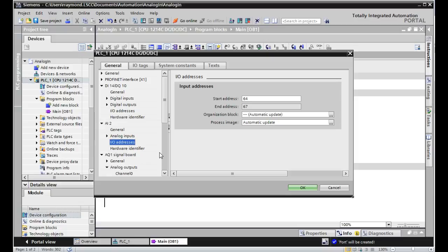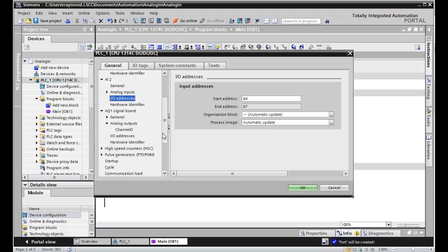It's just like when we set up our memory, it automatically assigned it memory byte 0 and 1. And of course, what we wanted to use was 0 and 1, to make it easier to translate the Allen Bradley addresses over to the Siemens addresses. So we got B3 0/0, and we can make it M0/0, .0. It just made it a lot easier. So all these guys are assigned ports.